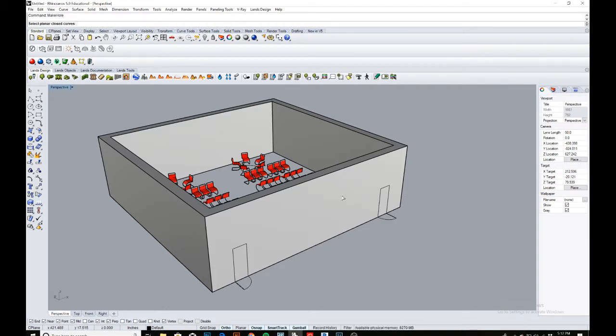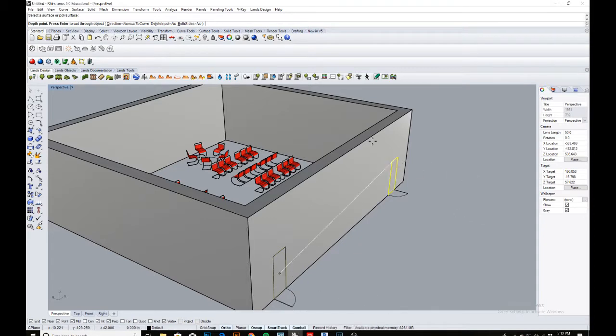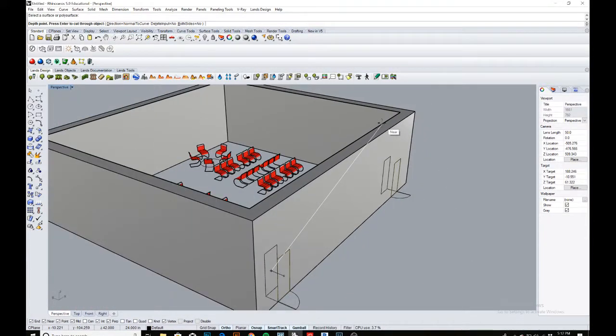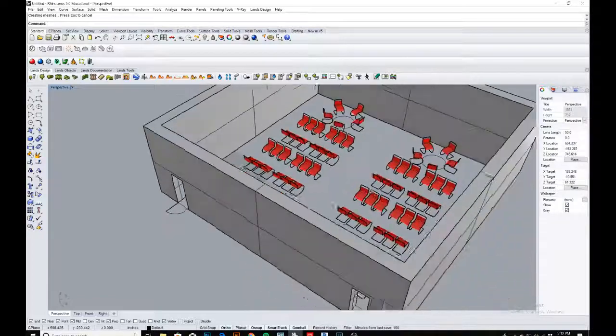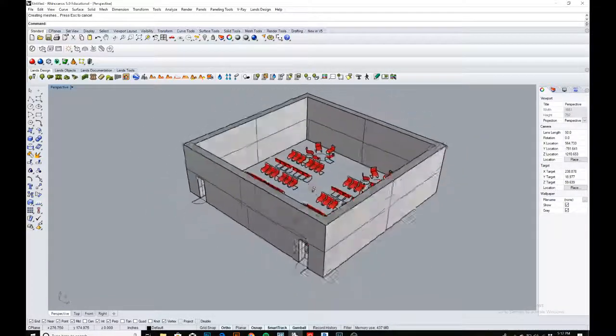Now it says select my curves. Okay, selected them. And then I'm going to enter, and then it says select surface, which is my wall. Selected it, and now it's asking for a distance to cut through. We don't want to cut this way. I can literally just put my mouse on the other side of this wall, and it's going to register that as the distance. And boom, already cut through. So that is how you model it.